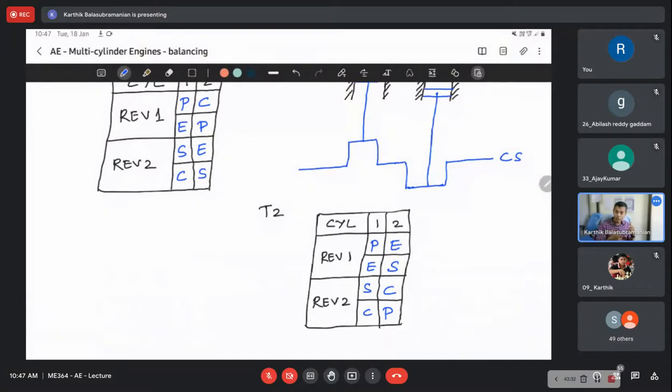2 full rotations. So if you go for 2 cylinders, you will have 1 full rotation and 1 rotation will go empty for the crankshaft. But if you go for 4 cylinders, then the same crankshaft is repeatedly receiving power strokes. So there is an overlap of power. This is what I meant by overlap. Sangeet, are you getting what I meant by overlap? I think you asked it, right? Yes, sir. Now it's clear, right?